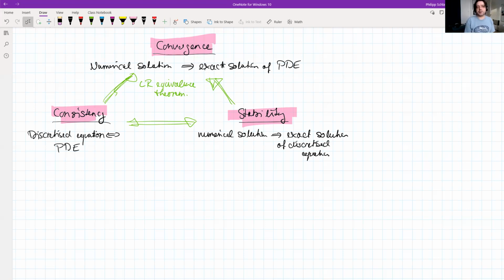It is sometimes possible: if you try to solve, for instance, a linear equation system, then of course you know exactly when your residual is 0, then you have found the exact solution. So in that sense, you can define an exact convergence criterion. But if you think of time integrating Navier-Stokes, you don't know that. You just have a bunch of different numerical errors, delta t, delta x, and you just want to know that if you grid refine, then you would converge somewhere.